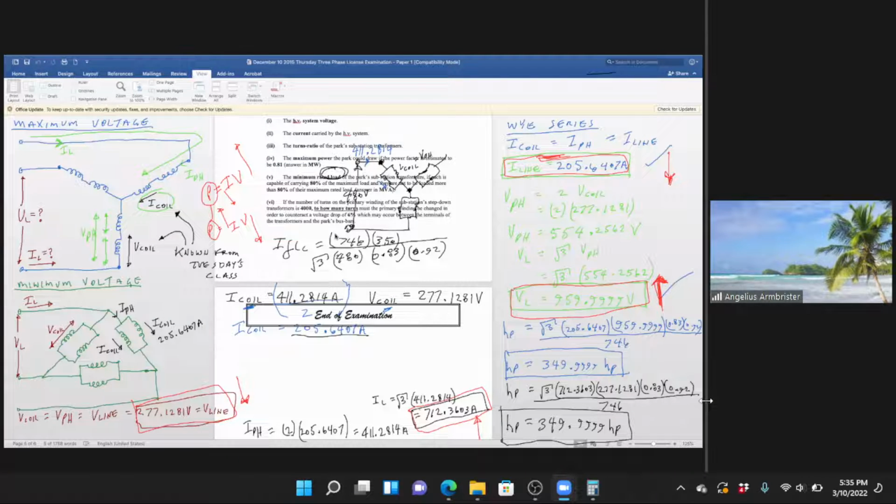But in any event, once you connect up a system, the load on that system is going to reduce the power system voltage. Don't care how much you try to regulate that, that's going to drop down some. And so therefore you have to have some kind of possibility to counteract the drop. And so this is what this question is asking you. One method of counteracting the drop is to put taps on this transformer, on the secondary or the primary. This question is asking you to change the primary windings.